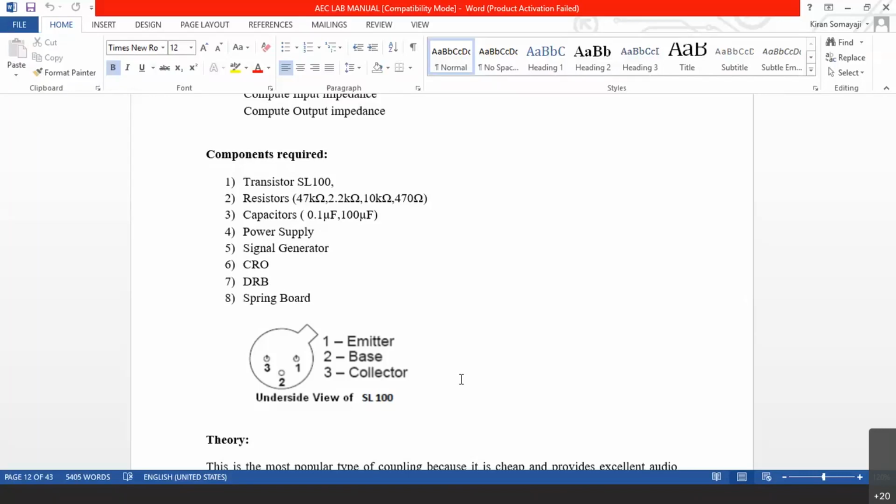So the point I am trying to tell you is, in the active region, the transistor consumes power. In the saturation region, it does not consume power because voltage is zero across it. In the cutoff region, it will not consume power because current is zero across it. But in the active region, neither the voltage is zero nor the current is zero. Voltage is half of VCC, current is half of maximum current. So there is going to be power consumption.